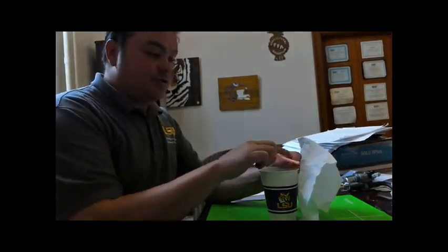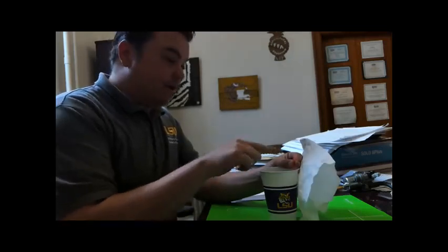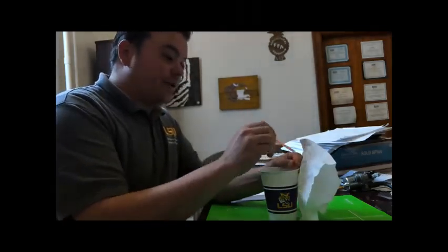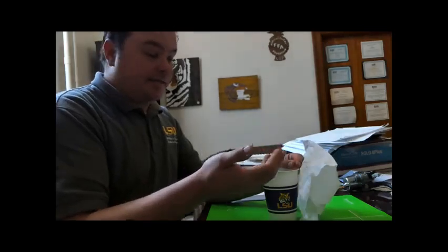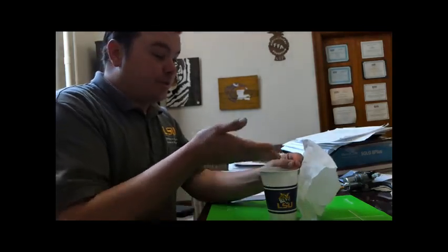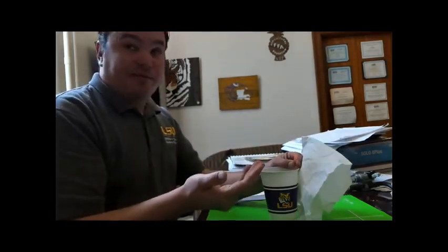So I'm simply going to blow air straight across the straw that is in the water, and that increase in velocity of the air moving over the straw will actually create an area of low pressure right at the top. And when we have areas of low pressure, nature basically just seeks equilibrium, and so water is going to be pulled up the straw and should, hopefully, if this goes well, be captured onto this paper towel. So let's give it a go.